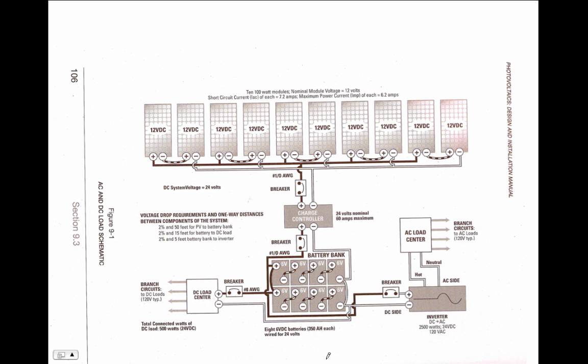Oh, one thing I wanted to point out on the battery bank is that this is for 8, you can't put 10 batteries in this system. You have to put them in groups of 4. So if you had 10 batteries, 2 of them wouldn't be usable. So if you wanted to add more capacity here, you'd have to have a 12 battery system. If you wanted to go beyond that, you'd have to have a 16 battery system.